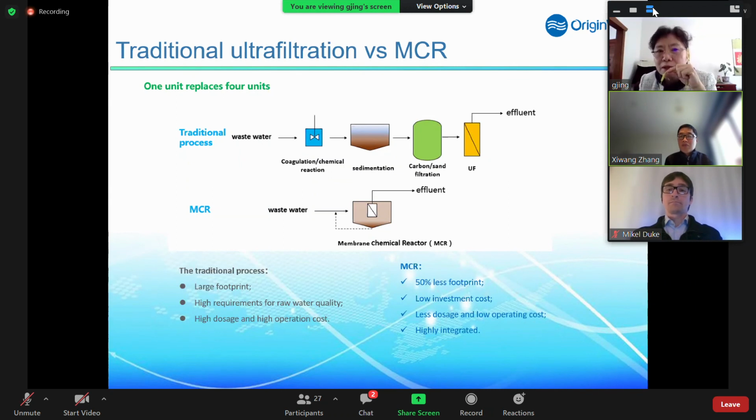I think that application we also use for some other MBR processes. If we only consider filtration, we don't need to consider settlement, or whether they completely settle. We can get water coming out from the top. So it's a kind of filtration process. As long as we can make the particles good enough to be stopped, that will be good enough.